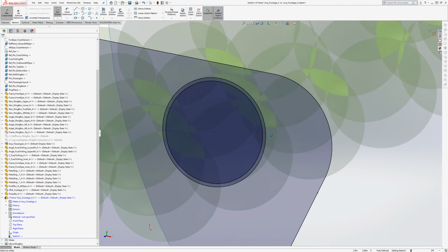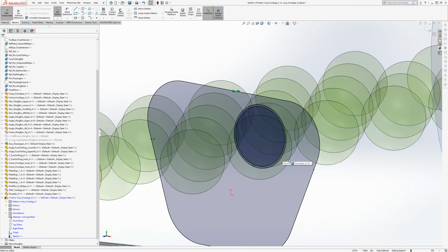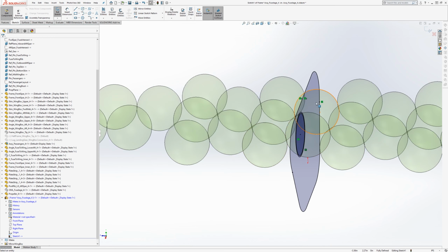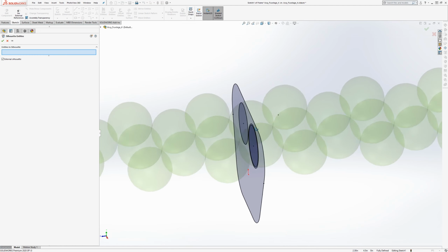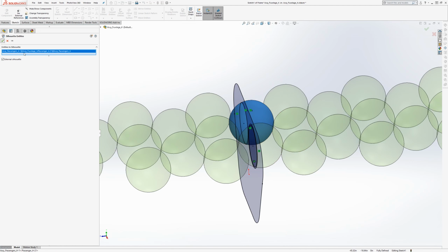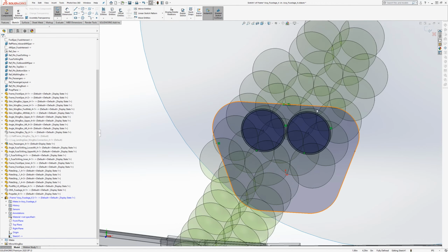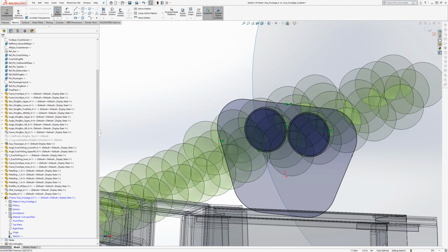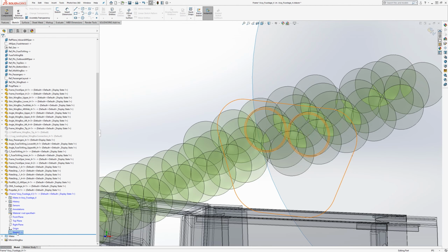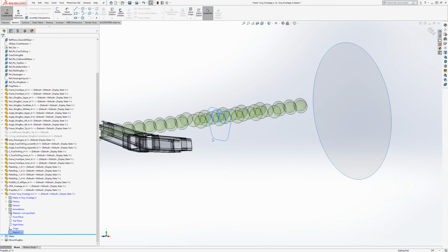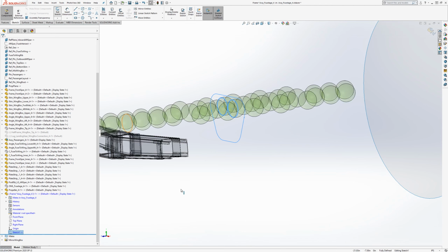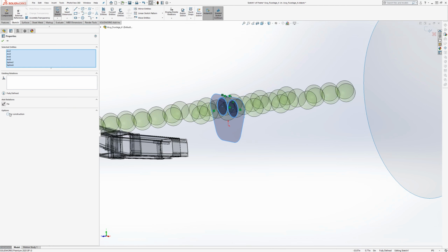We want to take the silhouette, which is the biggest portion of it. For instance, if we take intersection or silhouette. Then usually I would keep the external references to a separate sketch and actually make this all construction geometry.